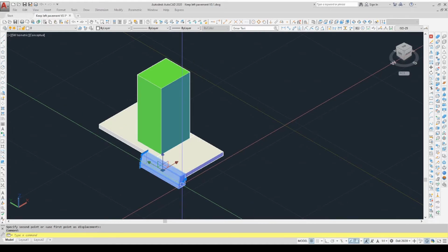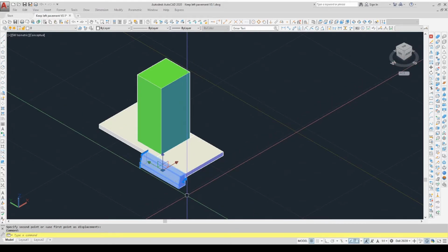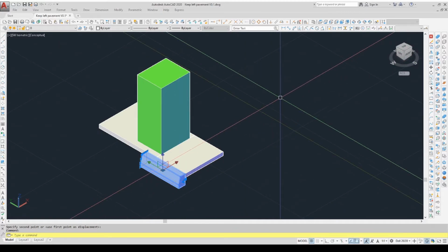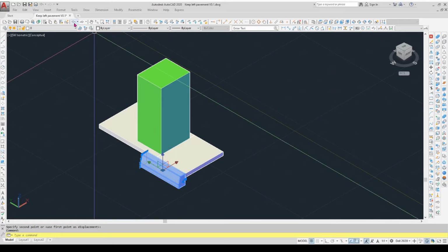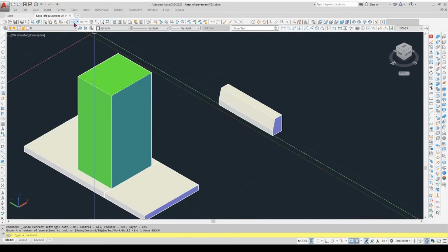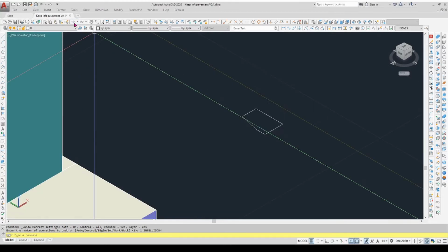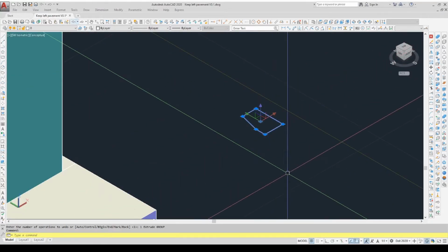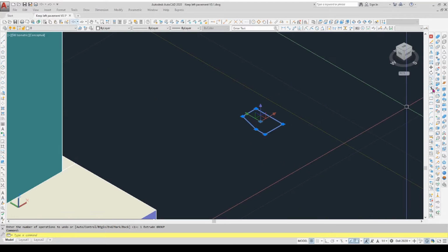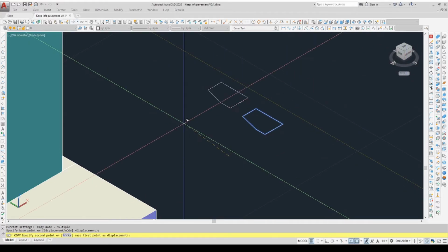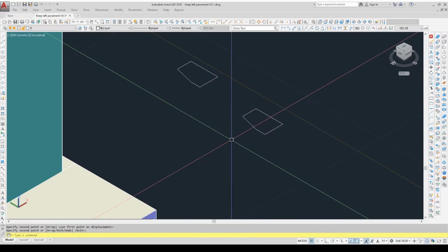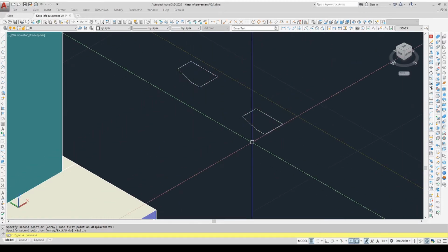But before we get to that bit, what I want to do is to make some slightly rounded ends, which means that I need that profile that I've just used that is now gone. But the good thing about CAD is that you can go backwards, and essentially it remembers every command I've ever used. So if I press this go back, eventually it gets to the point where I had my profile. And what I can now do is to copy that to there. Now I can go back and use that one as my curve.